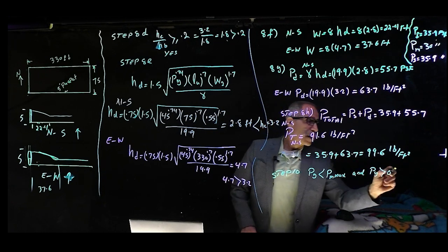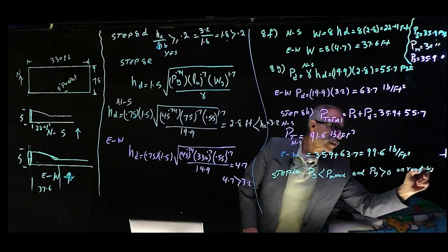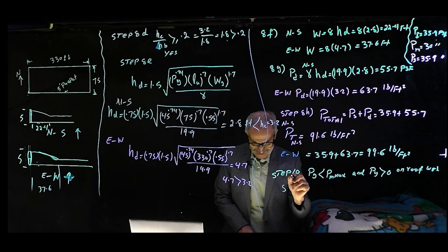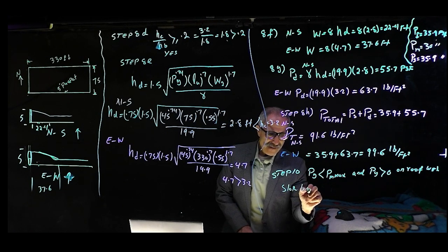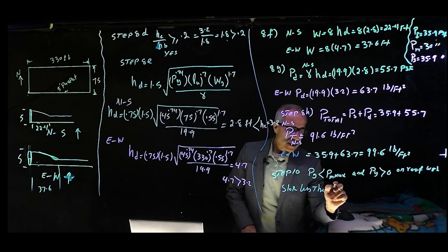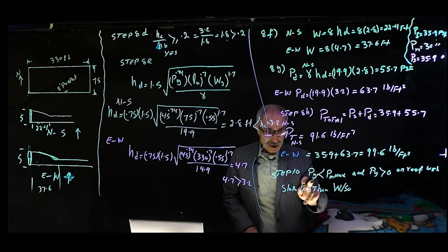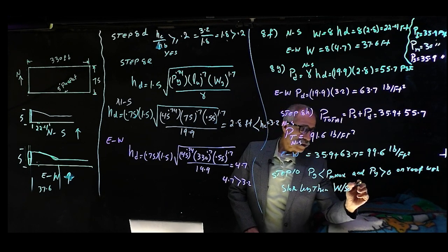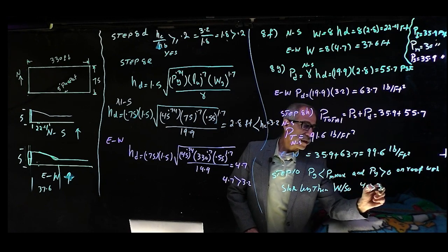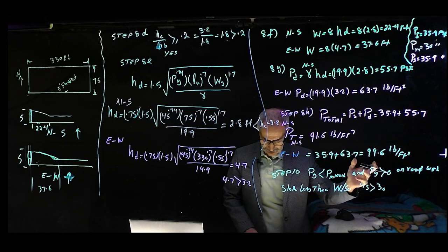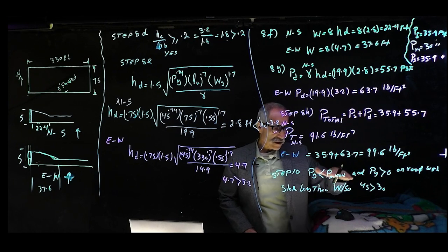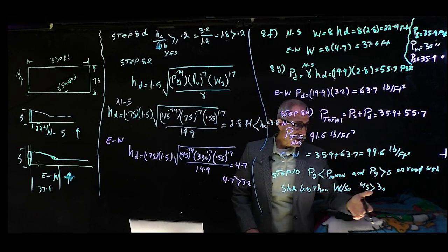Therefore, on a roof with a slope less than W divided by 50, and PG is 45, it's more than this, we have 45 more than 30, and the roof doesn't have a slope less than W/50 because it's a flat roof. So therefore we need to add a rain surcharge because this is a flat roof.